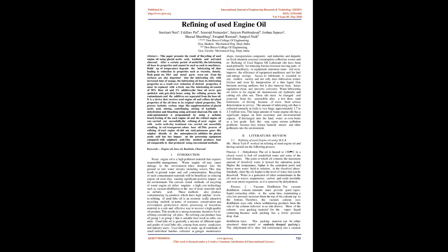The lubricating oil consists of 98% base oil and 2% additives. The base oil never gets spoiled, it only gets dirty. Hence, using the refining process, the contaminants and the additives are separated from the base oil.